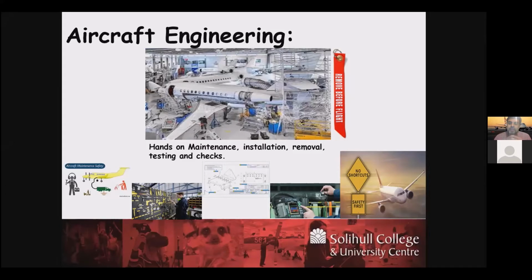We do checks on the aircraft, we look at corrosion, we look at fine cracks on the aircraft that may cause metal fatigue, and then later fractures. So in short, the aircraft maintenance engineer's job is to maintain the aircraft in airworthy condition, so that when it flies, we have the confidence that it's in tip-top condition, and nothing mechanical could go wrong with it.